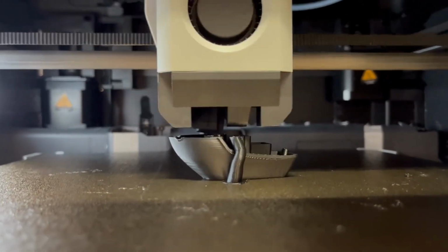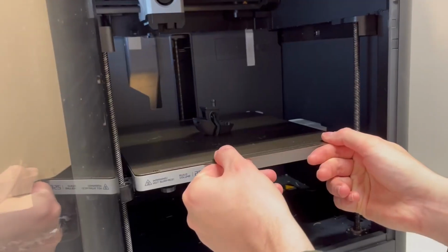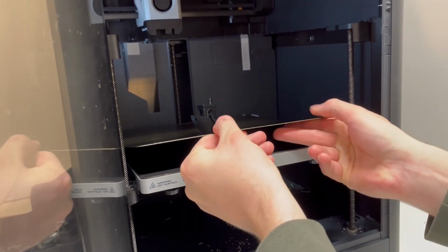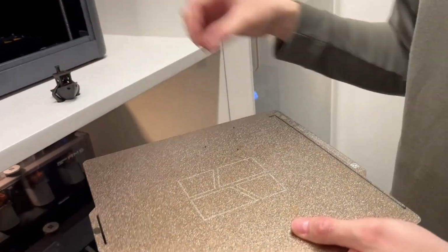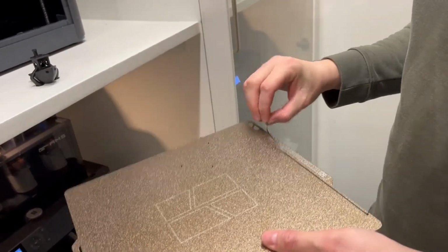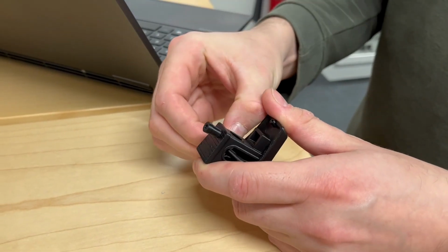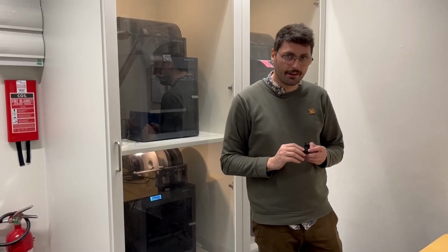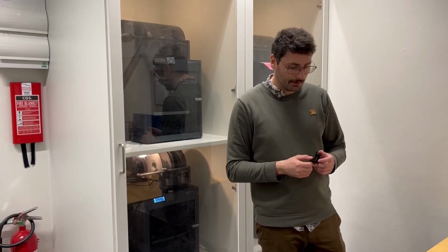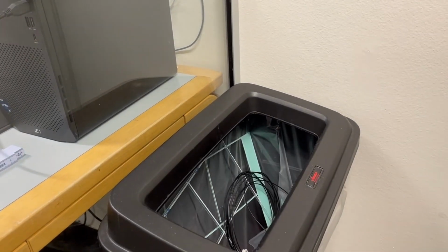Once the print is done, you can safely remove it from the 3D printer simply by taking it out. The plate is removable, and remember to remove all plastic from the plate, even the tiny strip that the 3D printer prints to purge the nozzle. If you're printing with support, now's the time to carefully remove the support from the 3D print, and you should be done. Congratulations, you've now completed your first 3D print. Remember to throw out excess filament.